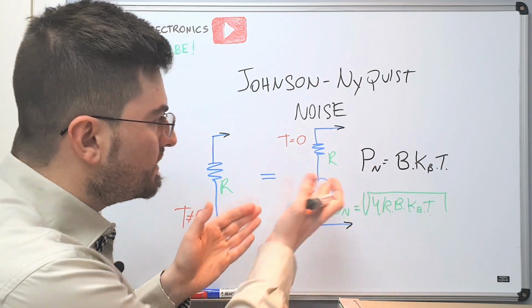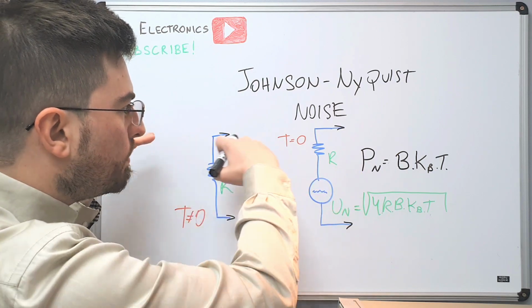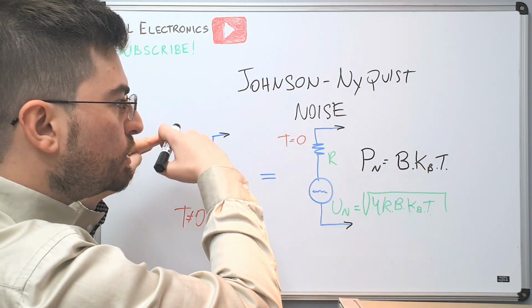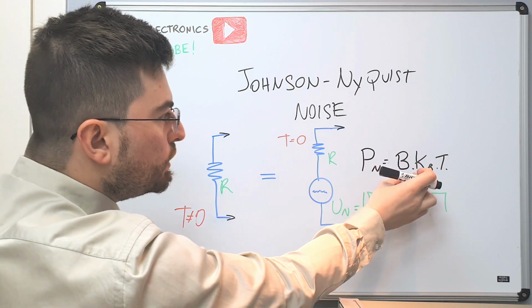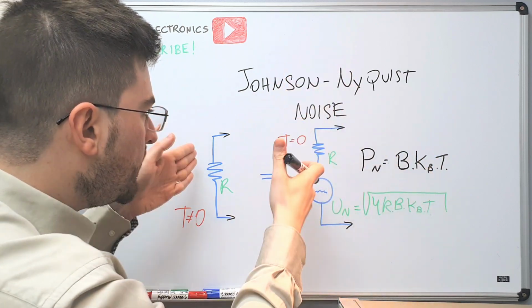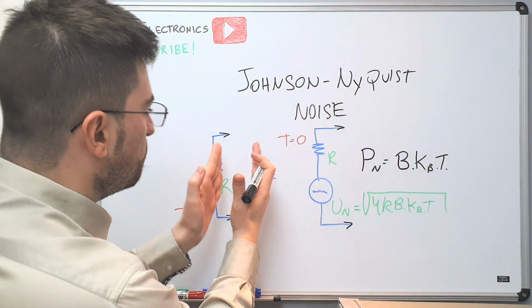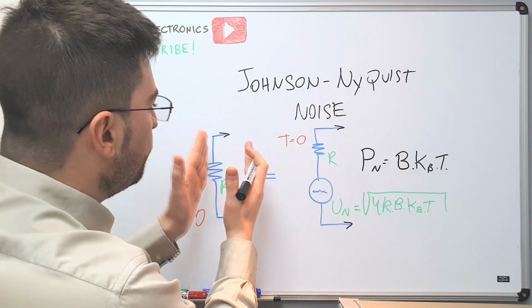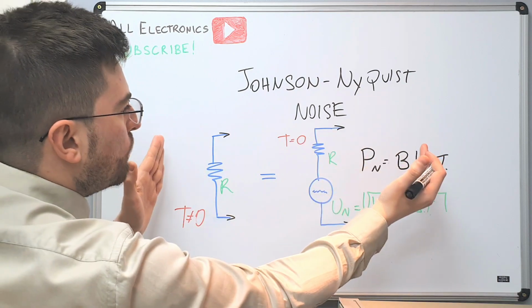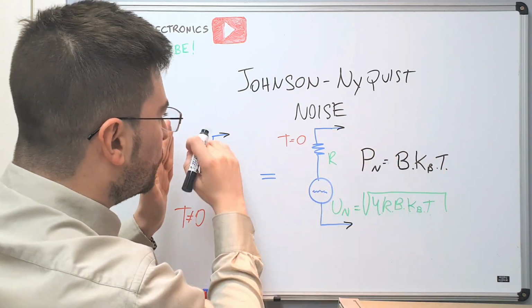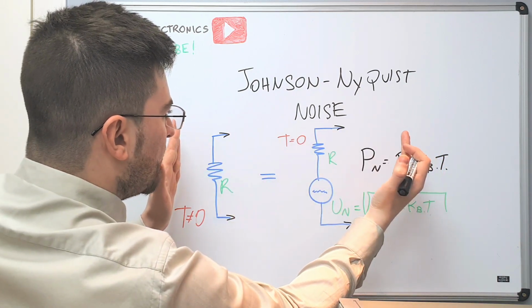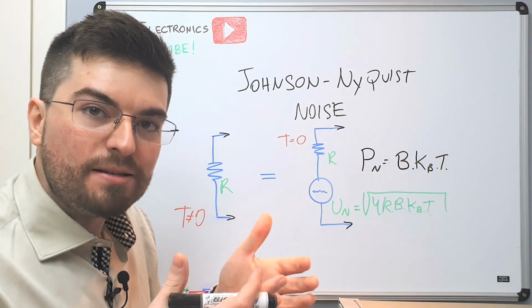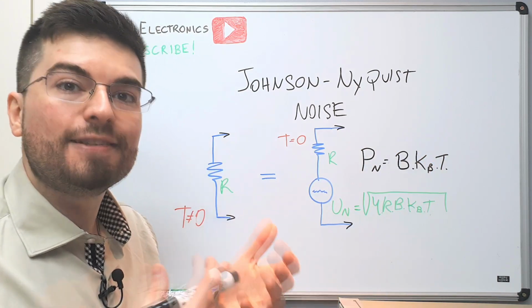And this is actually a power density here because we need to know the bandwidth. As the power noise density is broadband, thermal noise is broadband, we need to know the bandwidth we are working, because if the bandwidth is smaller, the noise we are capturing is lower than if we are working on a higher bandwidth where the observation of the noise power is higher. And now it will become easier to understand what a noise temperature is.